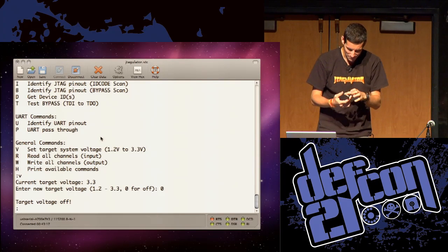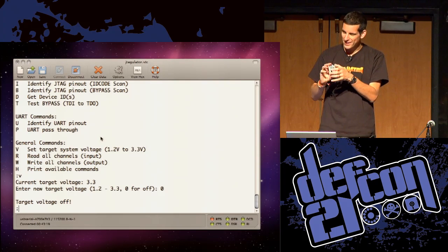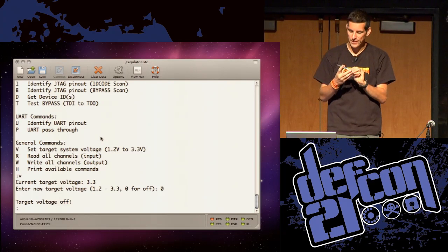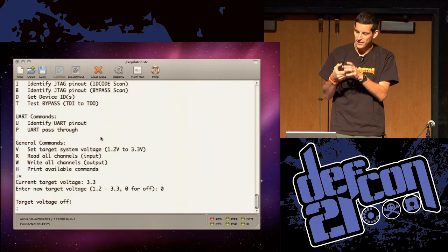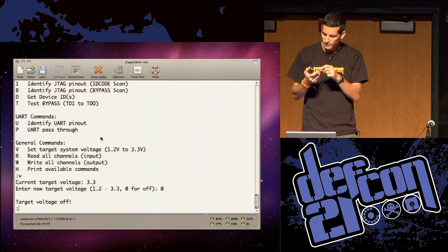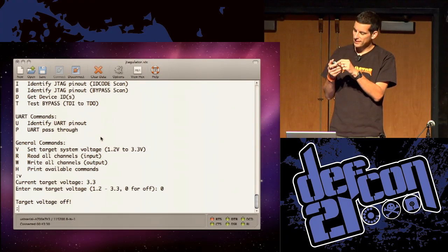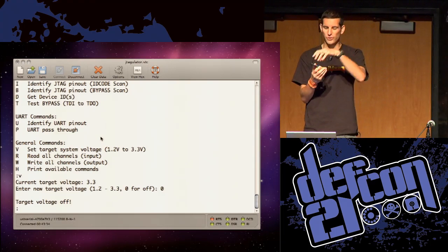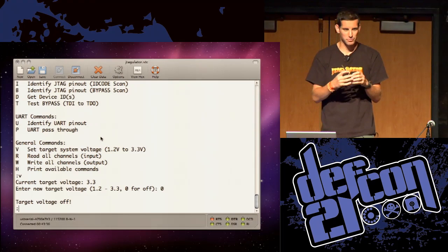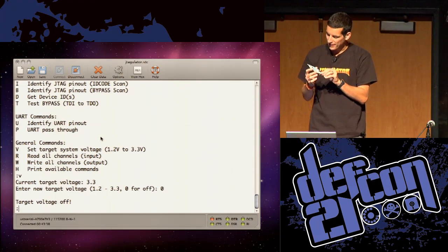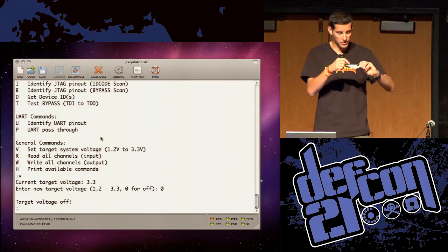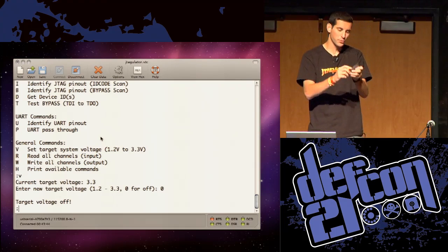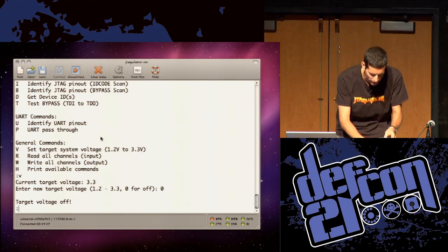Okay, 3 people. Okay, so the Defcon 17 badge had a Freescale MC56F8006. That was a digital signal controller that just happened to have JTAG on it. And I'd broken out the different pins as test points on the board that we were using during the badge hacking contest. You could reprogram the device and everything because they would constantly get bricked when people were trying to write code for them. So doing development, I just took all those test points, wired it up to a connector so I can connect it up to here and give the demo. But in real life, you wouldn't have a connector there, right? You would just solder wires on or something.